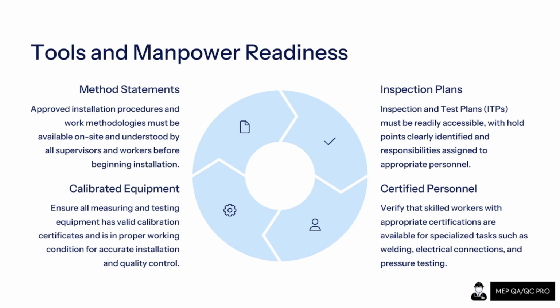If people don't know the procedure for starting a work, which drawing they have to use, where the hold point is, who can give you an NCR, who can take the identification and responsibility? So all this is the essential tools and manpower readiness requirement which needs to be followed prior to starting the installation.